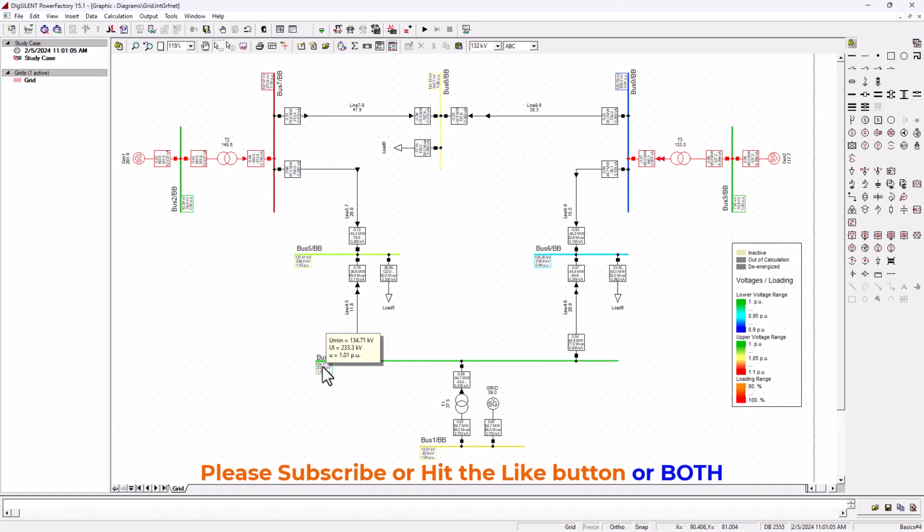Now, if we zoom into bus bar 4 here, we can see we got 1.01 per unit, and it's 233. So it's not too bad, because this bus bar is supposed to be at 230. Now it's sitting at 233, which is not that bad. And the single phase is on 234 instead of 232. Now, if you look into your lines here, we are very much transmitting the correct amount of current since our lines are not overloaded. But the transformers, right? This transformer is overloaded, and this transformer as well is overloaded, as well as the generator. So, and particularly bus bar 7 is very much overloaded.